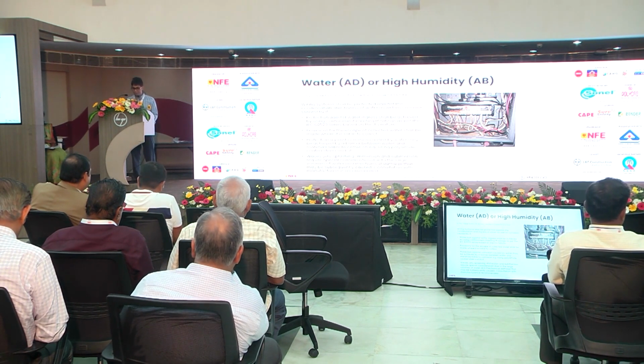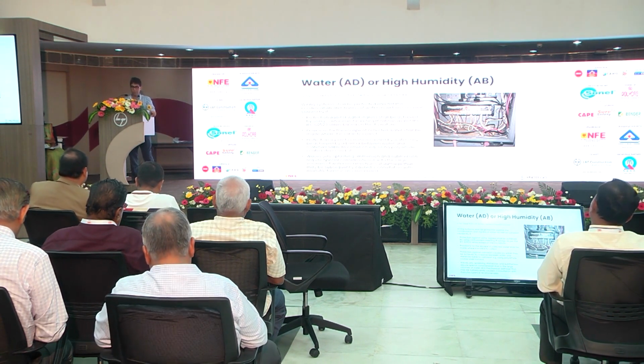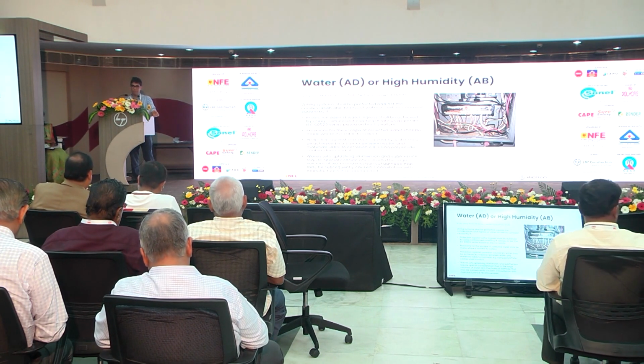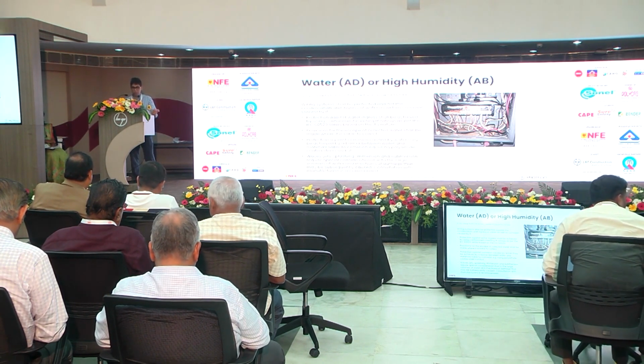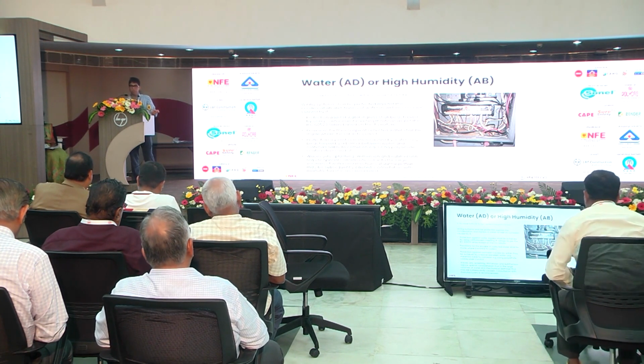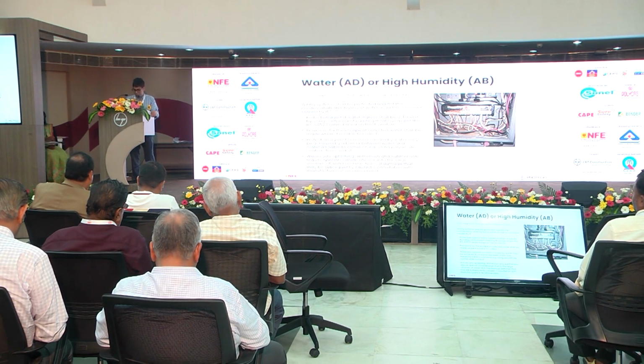A lot of times, you need a robust system like steel for conduits, but steel is not going to react with water very well. Galvanizing is one option which also comes off, but using simple things like polyamide coated steel conduits, there are a lot of manufacturers in India that manufacture this, means you don't have to worry about this.